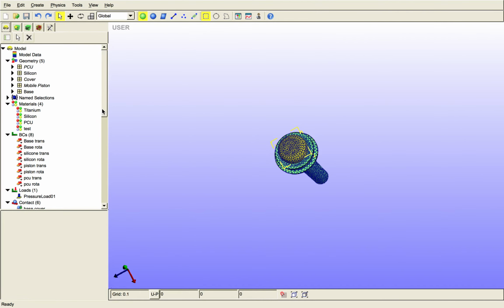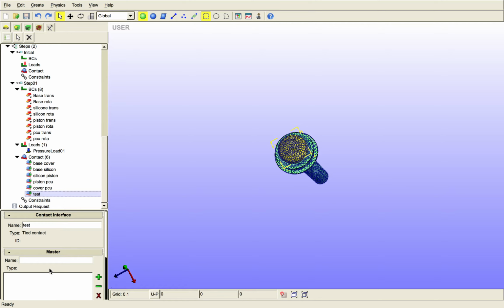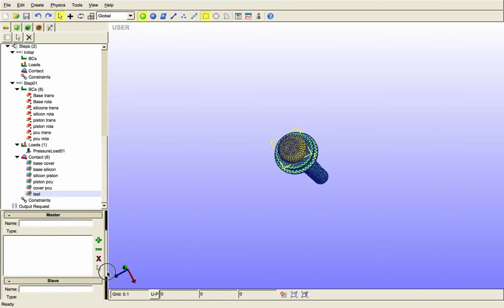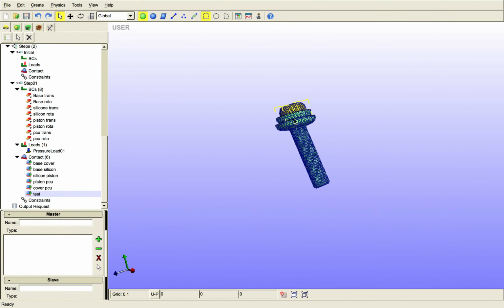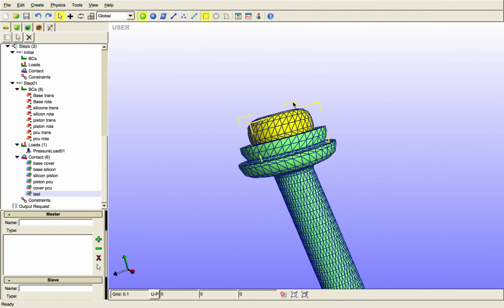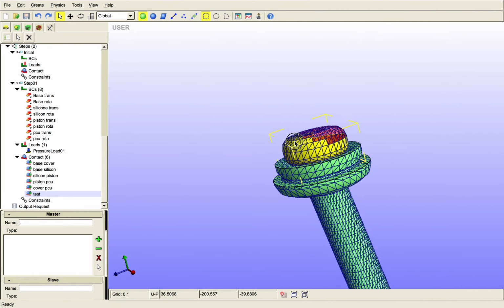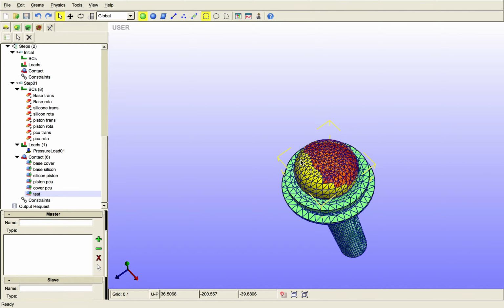Come back to this. Test for the contact for the master. I chose it as a master, but it's just an example. And just simply select elements with shift, for example. Keep pressing shift, and you can choose even zones and add them.